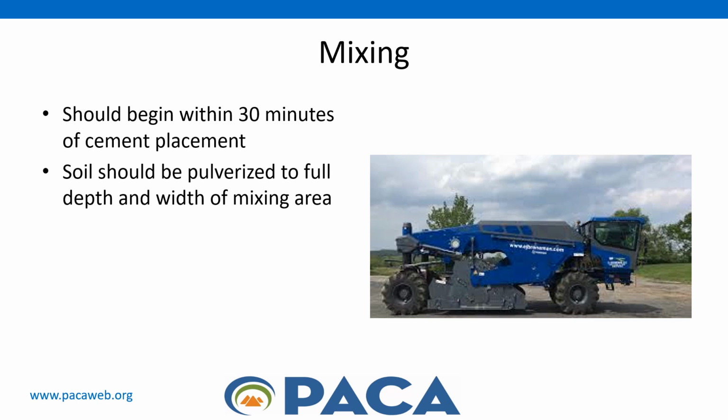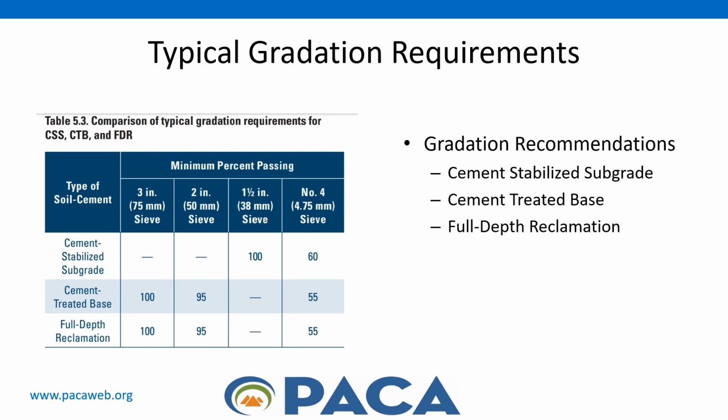After the cement is spread over the surface of the subgrade, the next step is to mix the cement into the subgrade material using equipment such as a reclaimer. This mixing should begin within 30 minutes of the placement of the cement. Remember, it's important to sufficiently pulverize the soil to the full depth and width of the mixing area, especially for those cohesive soils such as silty clays and clays. The finer the soils are pulverized, the more effective the cement stabilization treatment will be.